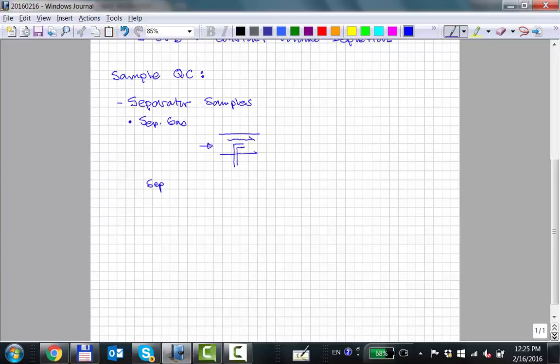So the gas is flowing along here, and then they have this 20-liter container. And the pressure at this condition of sampling is very close to the separator pressure. Okay, there shouldn't be any pressure losses between the separator and the point of sampling.